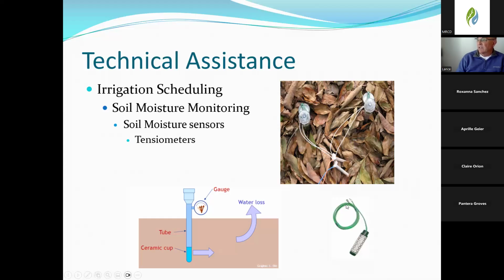The device on the right here at the bottom is a watermark, also made by the same company as the top, the tensiometer. The watermarks are a block of a matrix. It used to just be made of gypsum, but they now make them of a composite material because gypsum breaks down too quickly. So this is a porous material. Water can move through past that metal screen and across the block.